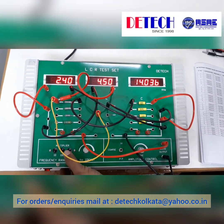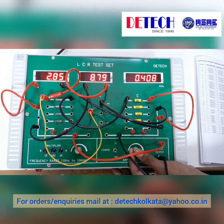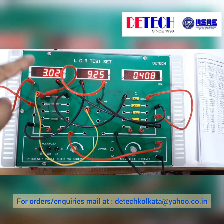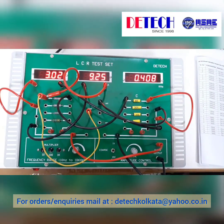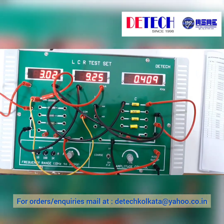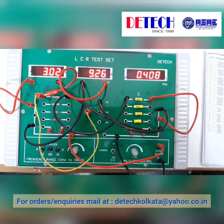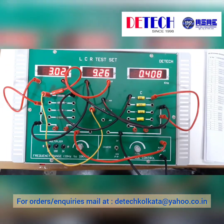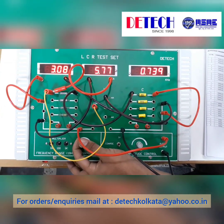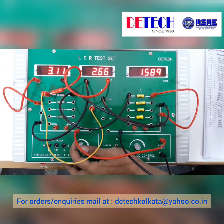So I've switched on the circuit. We are pressing the multiplier 1K, and we are now setting the input voltage at 3 volt. You can see in the voltmeter here, it's set at 3 volt. The current here is 9.25 milliampere and the frequency is 400 hertz. So we'll change the frequency and the current will start to decrease initially, and at the resonant frequency it will be at the minimum value and then it will start to increase.